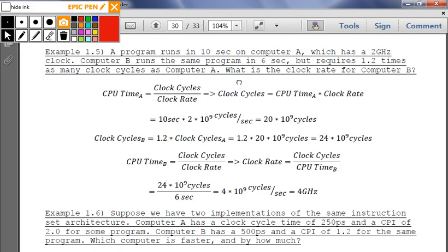You have to get from a 0 to 1 in a certain amount of time to represent the information if you're switching. So if your frequency goes too fast, before you can get up to about halfway before the next piece of information is coming in, if you overclock it, it never properly gets to 1. So that's a limiting factor. The actual implementation technology is a limiting factor in itself.